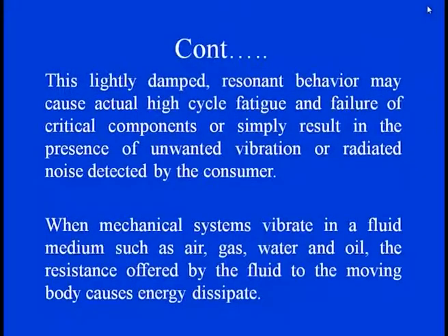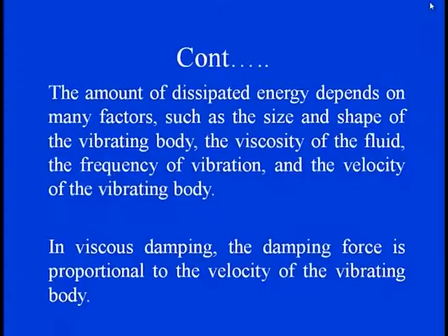So, when the mechanical system is under vibratory condition, even in a fluid medium like air, gas or oil, the resistance offered by the fluid to the moving body always causes energy dissipation. The amount of this energy dissipation depends on various factors like the size and shape of the vibrating body. Another important feature of the transmitting media is the viscosity of the fluid.